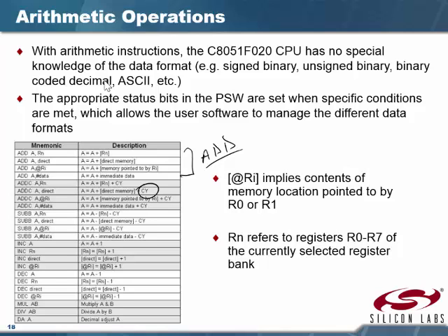So we also have the subtract. Now the subtract always takes into account the carry flag. So we subtract 2 numbers from each other, and we also subtract the carry flag. Because again, when we subtract, we want to do a borrow. You subtract in the same direction, least significant byte first.